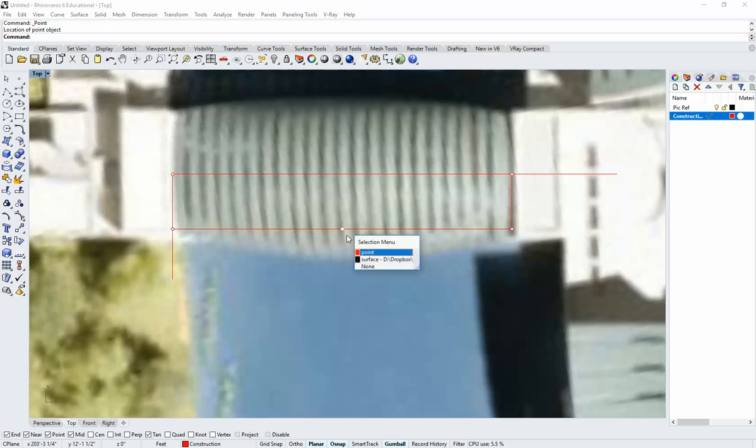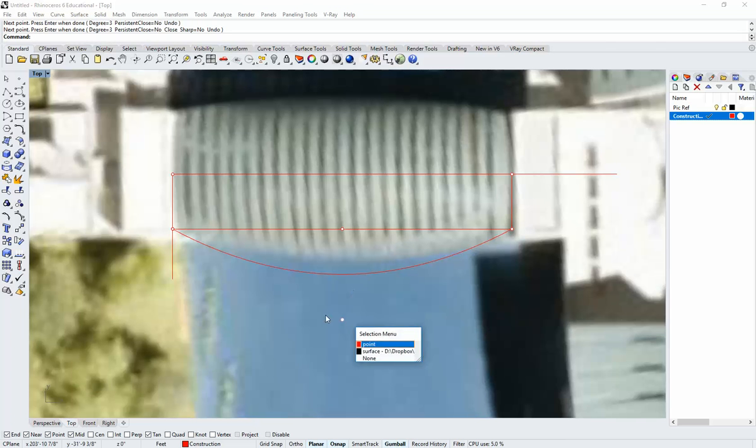So what I'm going to do is I'm going to copy this point, holding shift down a bit somewhere like that. And we can adjust this later, but I want to make sure that when I draw the control point curve that I'm putting a control point exactly in the center of this curve here. So I'm going to go over to my control point curve over here. I'm going to click those 3 points like this, and I'm going to end the command. Okay. You could get rid of this point if you like.